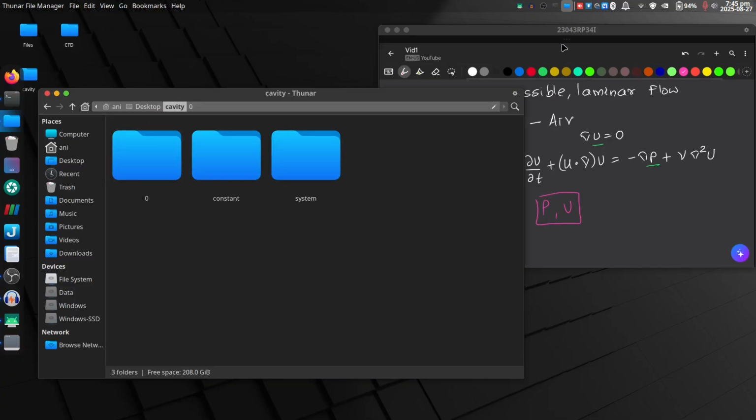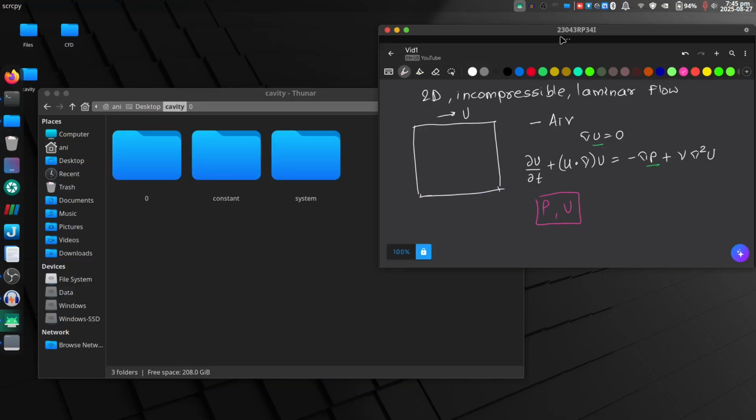So this checks, right, that we are solving for these two fields, and the boundary conditions are that on the walls U is 0, V is 0, and that condition applies on all the walls. And on the top wall we have U is equal to 1, V is equal to 0. Again, the third dimension is obviously going to be 0, needless to say, right?